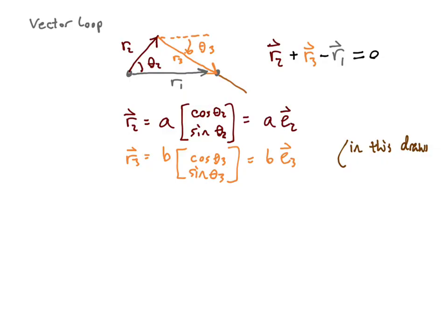But when we look at R3, we can see that there is clearly a negative y component, but I don't show that in this matrix. And the reason for that is we are measuring relative to the horizontal. If you measure below the horizontal, that gives you a negative number for theta 3. And with a negative theta 3, we would end up with a negative sine theta 3. So theta 3 is a negative number, and so that means that cosine theta 3 would stay positive, sine theta 3 would turn negative. And just in case you had that as a question, we can point that out.